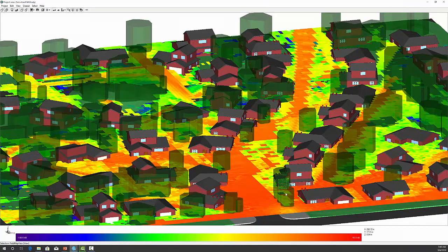And we can see some clear things happening here. There are some very strong fields that move forward. This is signal to interference plus noise. So we see some very strong levels of 40 to 50 dB in the direct line of sight, but we see some very sharp shadowing just behind a few trees and behind the houses as well. So as expected with millimeter waves, we have very strong line of sight and we have deep shadowing. And these are the effects that are going to be coming into play when we start trying to see how well our system performs in this neighborhood. This winding road is not going to be helpful when it comes to shadowing.